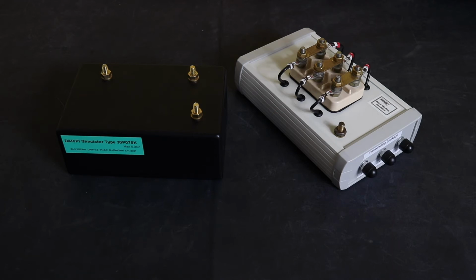This particular video is going to be regarding the polarization index simulators that I built up to test the MTR 105. I needed to build a unit with a higher resistance range than the original unit that I had, which you see on the right there, which is basically a simulation of a three-phase motor. It has 3 windings built into it and a simulated polarization index circuit between each winding and earth, and I've also developed it later on to have leakage between each of the windings, which are the 3 connections that you see at the end of the case there, and that then adds a further testing element to the design.